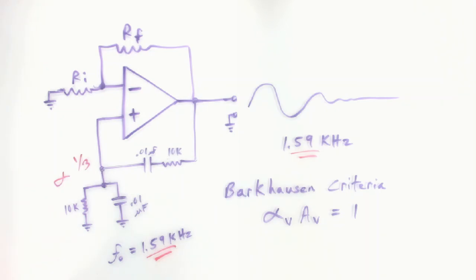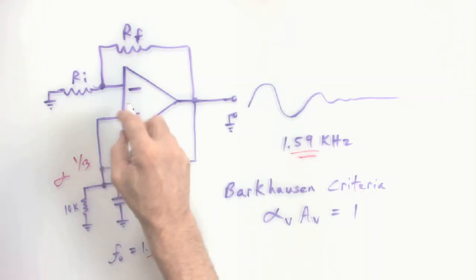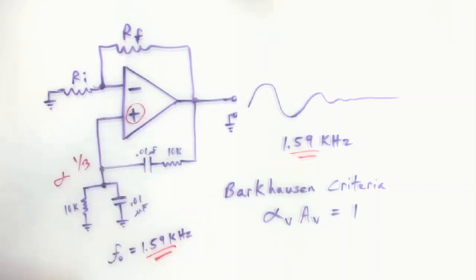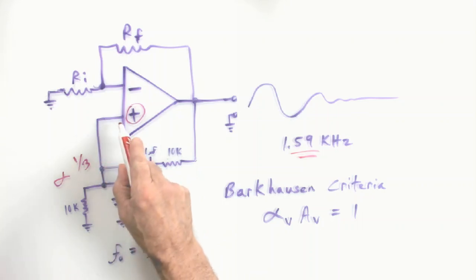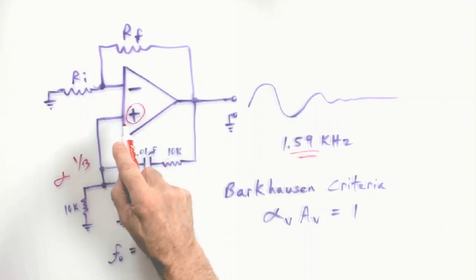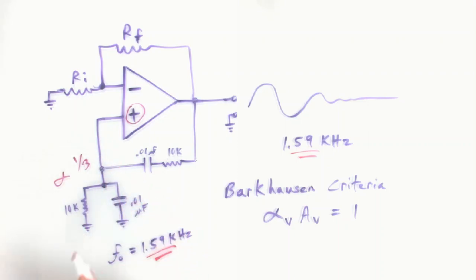If you look at our gain then, here's a time you don't want to forget about this, although I often do. If you think about it, our feedback is coming in to the non-inverting input. So don't forget that +1.